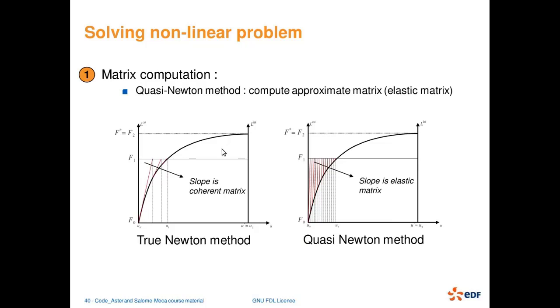And another way to totally avoid the computation of the tangent matrix in a given time step, in every Newtonian iteration, is just to use the elastic matrix. That is, the first tangent matrix will be used over and over again in the time step, and thereby I will gradually reduce the residual and finally achieve the correct solution. This is shown here. The same tangent matrix is being used, and thereby with a large number of iterations I will be reaching the true solution.